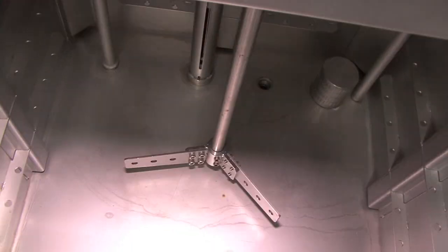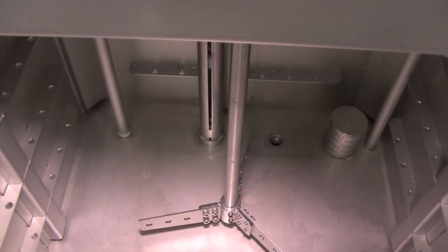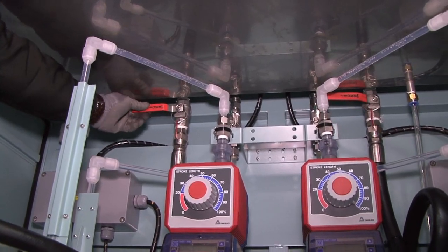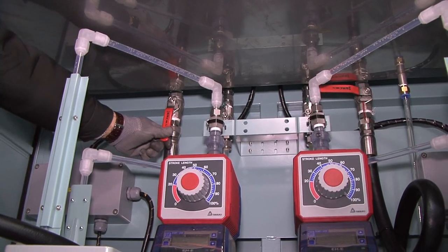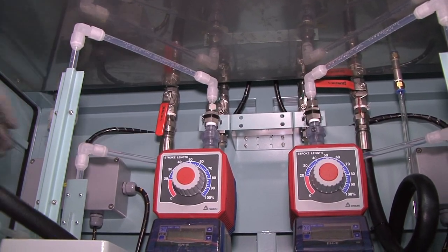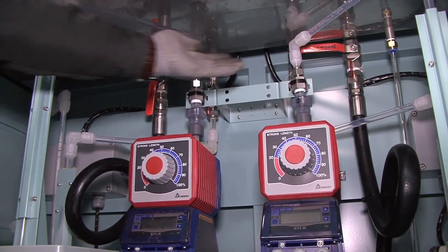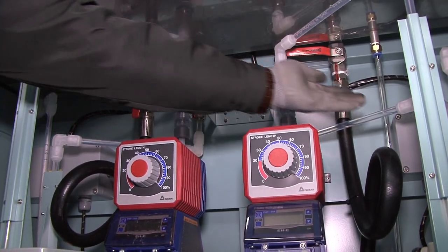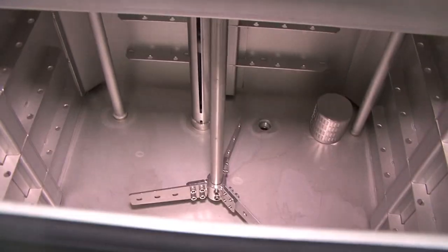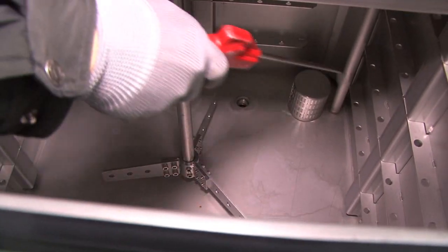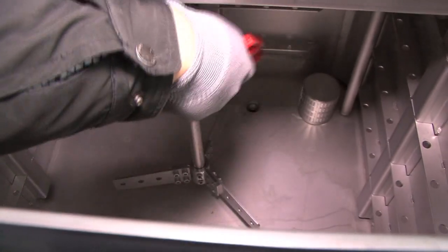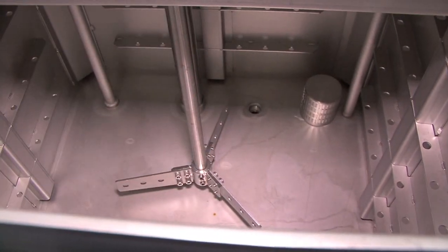2. ANU. 2-1. Cleaning strainer of ANU tank. Step 1. Open the valve of drain line and drain the remaining neutralizing solution from both left and right tank. Step 2. Clean both left and right tank with fresh water. Step 3. Clean the strainer with compressed air, 4 to 7 kilograms per centimeter squared.